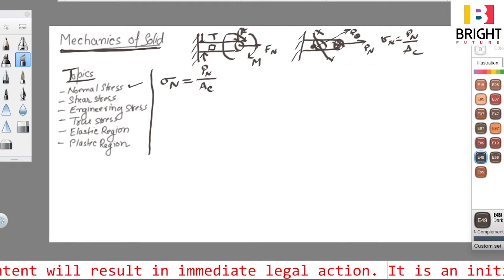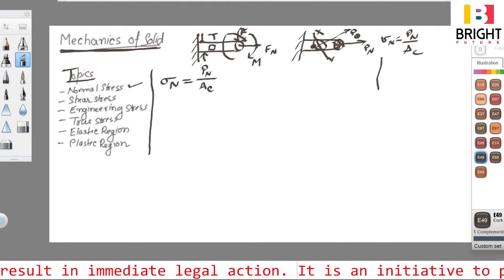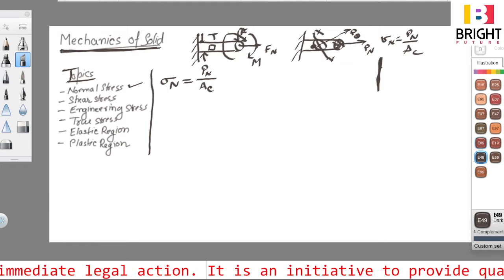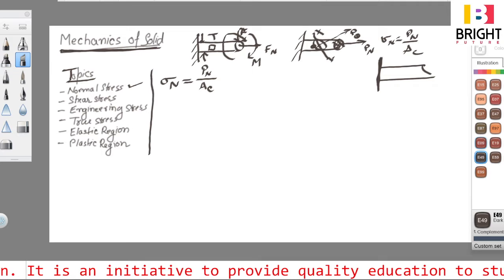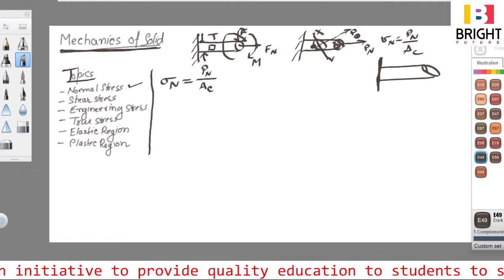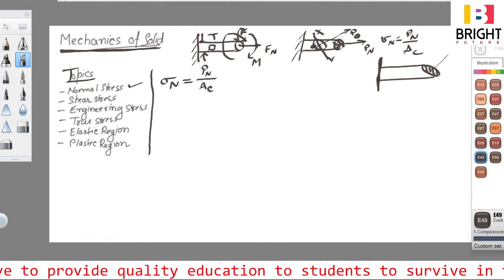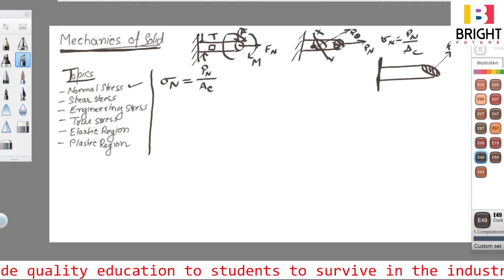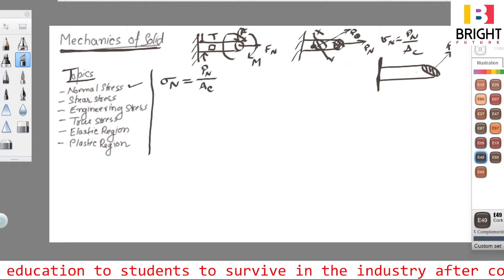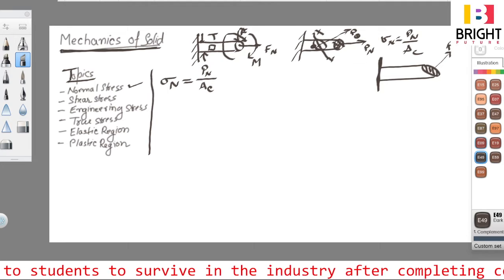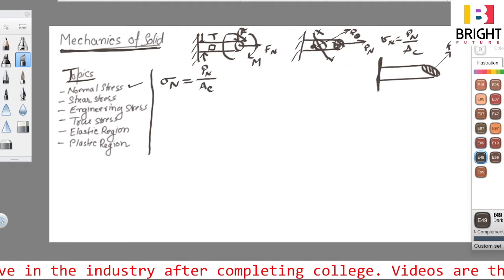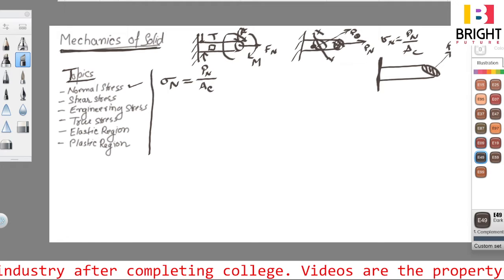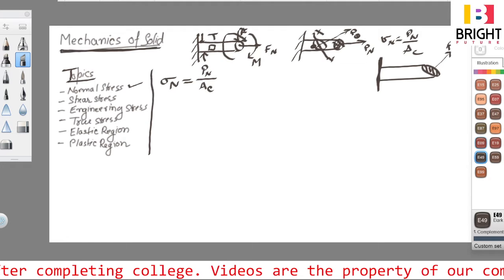You must understand that if we cut a cylindrical rod like this, the section will be an ellipse and not a circle, and the normal force will be like this. So this will be the normal stress. One should understand this fully, because otherwise in numericals there can be too many mistakes, right?